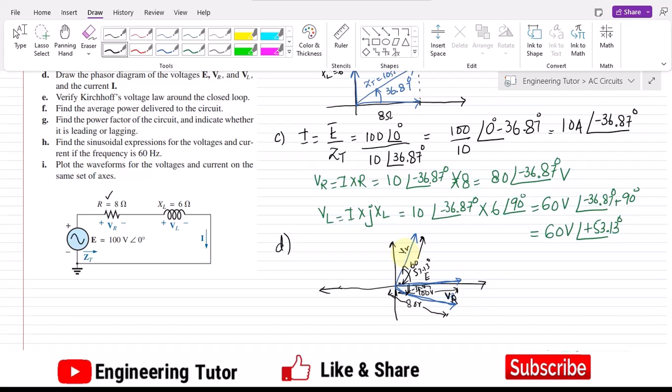So this is the phasor diagram for the voltages, but now we also have to draw the current here as well. For drawing the current, let me use this green color, and the current here is 10 amps and the angle with it is minus 36.87. Let me write it like this. So this is the current.